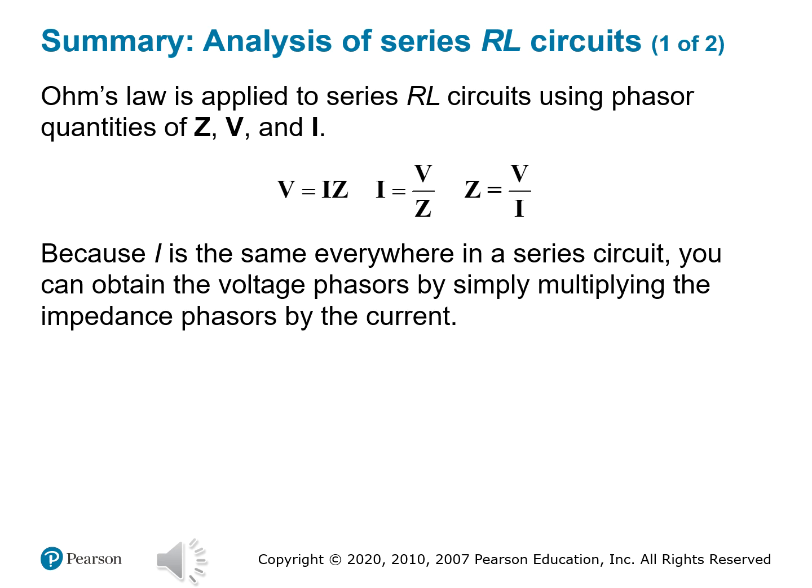But again, we're going to look at this through phasor notation. Remember that impedance is complex. So when we talk about complex numbers, Z is equal to R plus jX sub L. That's the form for that complex number. So when you multiply it by I, you get both the magnitude of V and the angle of V and I, and this lets you predict and control the following: the power delivery, the voltage drops, and the phase alignment in real-time AC signals.